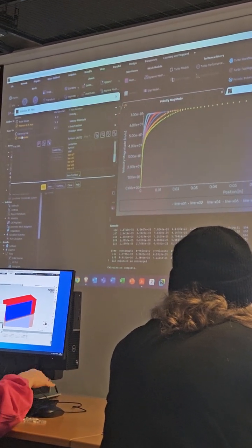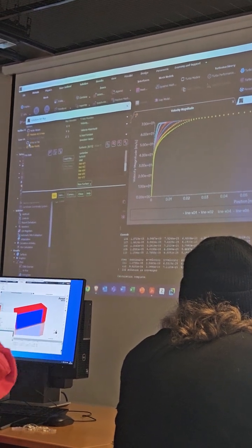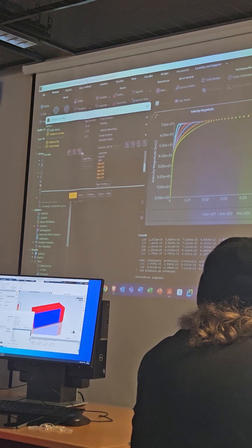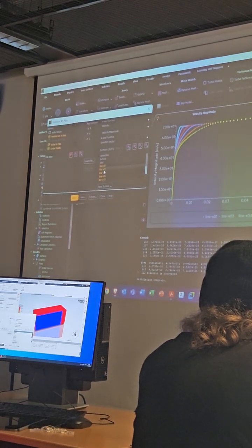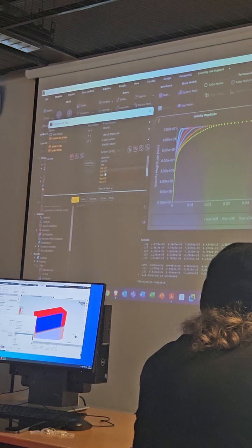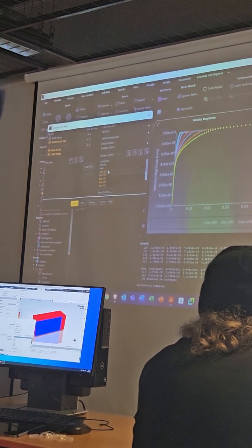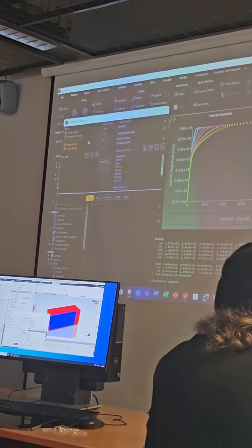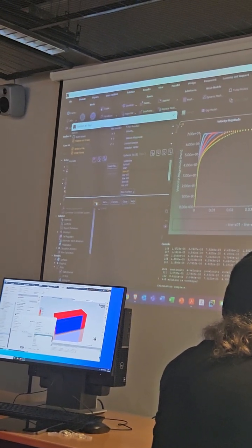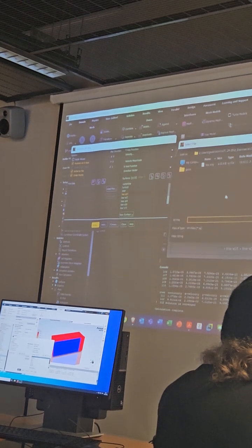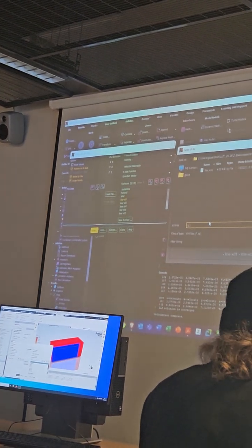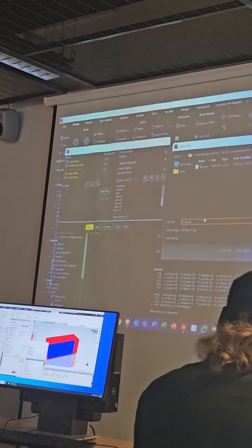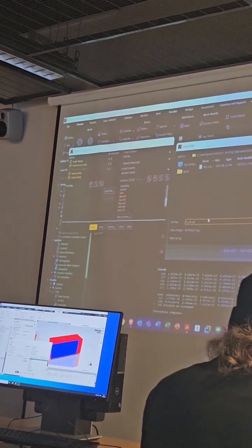And you can select the Write to file option once you have these charts, which means they are correct. We can write this either all together, but now I was thinking that maybe it's better to do separate files, so it's easier to copy into Excel. So I'll select just line x01 and write. This is going to be u01, so the velocity at x equal to 0.1, dot xy.